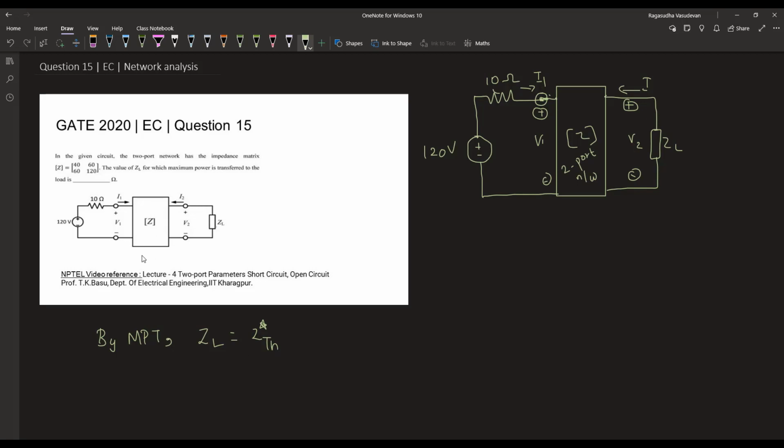In this network, we have a purely resistive DC network. Hence, there is no scope of reactance in the network. If we are connecting an impedance at the load, then according to the maximum power transfer theorem, the resistance of this load must be the same as the Thevenin's equivalent resistance of the source network.